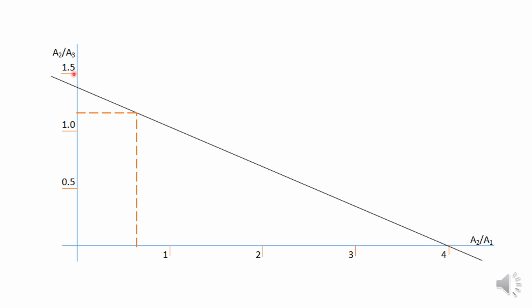So again, in the design of the truss, you can look up lists of cross-sectional properties of steel members if you're using steel, and try to find ratios of members close to this value and close to this value, and in that way you'll get a force, an F, close to -2.